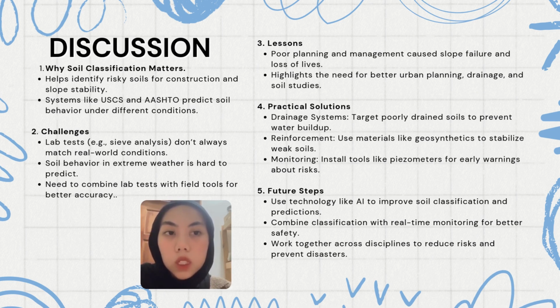Next one is practical solutions. We can solve these issues with a few key solutions, such as installing drainage systems to prevent water build-up. And second one, use materials like geosynthetics to stabilize weak soils and monitor the soil in real time with tools like piezometers for early warnings.